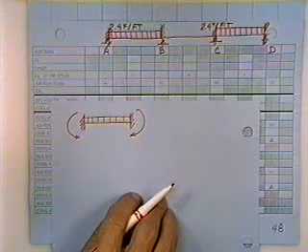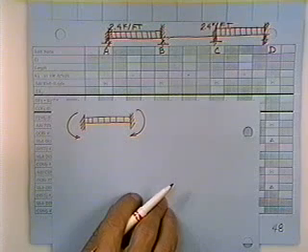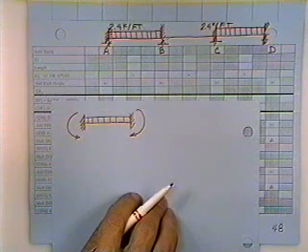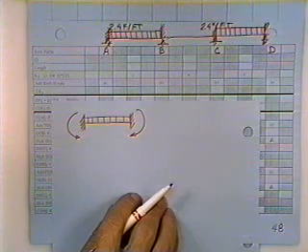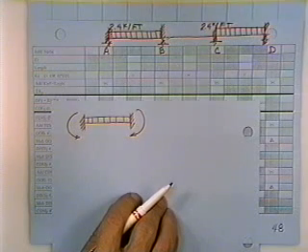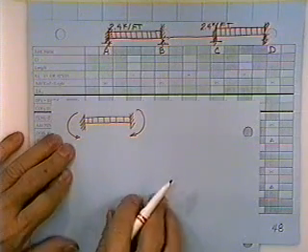All right. We want the case that shows a fixed beam totally loaded across its top. It's on page 13-21. It's the fifth one from the top of the page on the left-hand side. See, somebody's already worked out that kind of a structure and found that the moment on the left end is a negative WL squared over 12. Clockwise moments on the beam are considered positive. And on the right end is WL squared over 12.